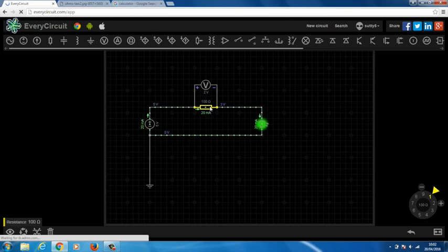So Ohm's law states that current is inversely proportional to the resistance. And to show what that means, if I increase the resistance to 200 ohms, so that's the inverse part of the equation. You increase the resistance, and therefore the current decreases. And if we decrease the resistance, so we'll take that to 50 ohms, so if we decrease the resistance, the current increases. And technically we're providing way too much current to that LED.